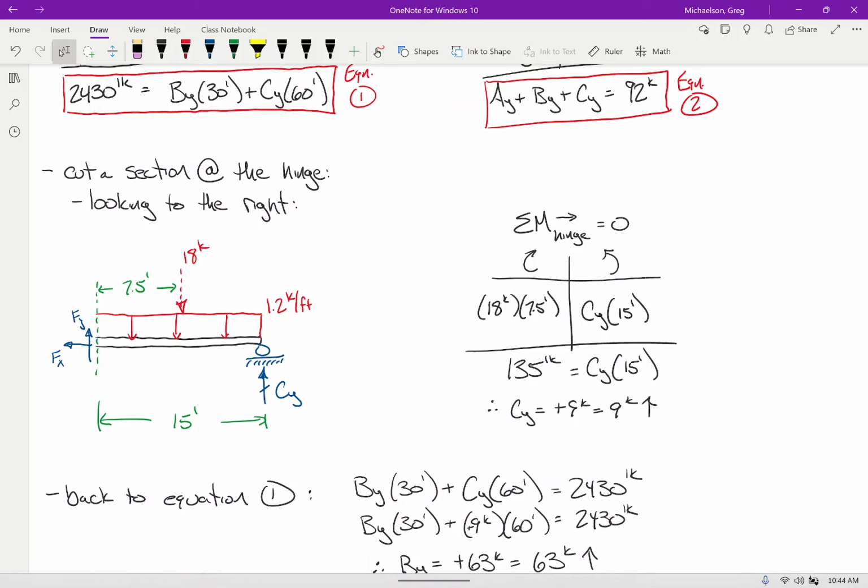One of the tools that we engineers use to this day is what's called an influence line. And we are going to learn how to do influence lines a little bit later in the semester. An influence line is a diagram that we use to assess structures that are subjected to loads that move. So when the loads move across the structure, that's what you use influence lines for. What type of structure do we design where the loads move? A bridge, right?